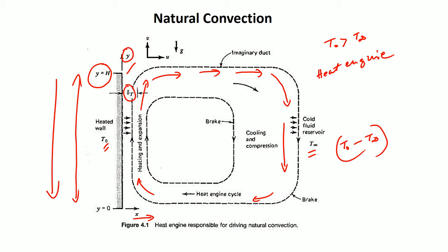As you know, as you go lower within a reservoir of fluid, your hydrostatic pressure goes up, because hydrostatic pressure is basically rho g h. At the bottom of the plate it will be rho g h, at the top it will be whatever is the value. So, this is very similar to taking a heated plate and immersing it in a reservoir of cold fluid, understood.